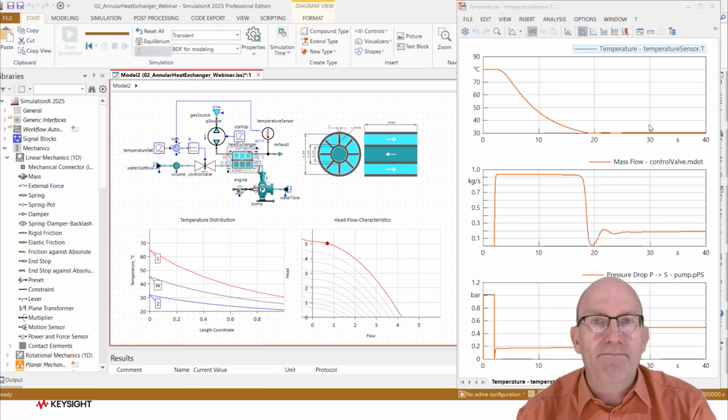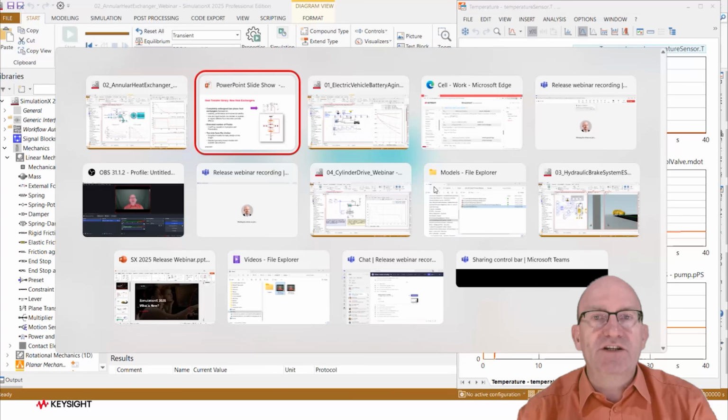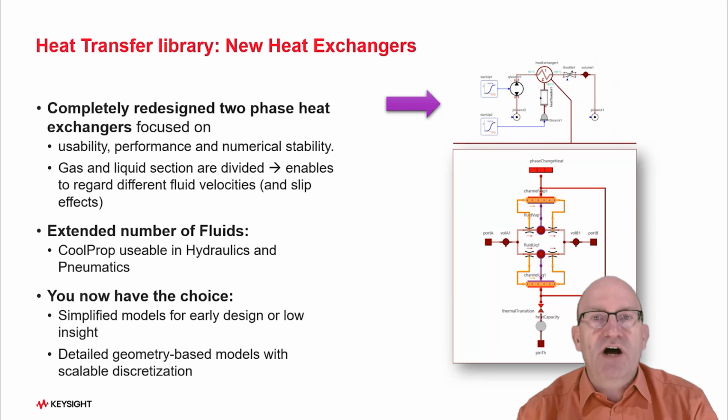And as a result, of course, this controller steers certain aspects of the process. So for instance, it shows here the control value. It's the amount of water flow which I need in order to achieve these temperature levels. In the beginning, apparently with high temperatures, I should have a big water flow. Here you can see it's saturated, so the valve is fully open. But then when I come to my target temperature, the valve gradually is closed, and I go to a certain level settings to allow the flow of water, which is necessary to get the hydrogen temperature from 80 degrees to 30 degrees.